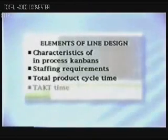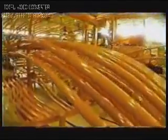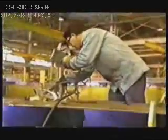Takt time is a tool that we use to size the equipment that will be required and to define our operations. Operations are established at demand of capacity. As the production requirements fall, the operations remain the same and people move from operation to operation, unlike splits, which are constantly redefined as the volumes change.